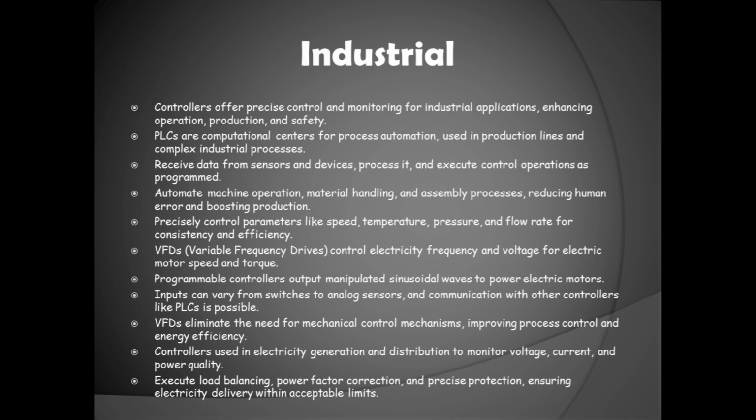VFDs also discard the need for mechanical control mechanisms like throttling valves or dampers by altering the motor's speed to fit the actual load needs. This improves process control, reduces equipment wear and tear, and saves a lot of energy.